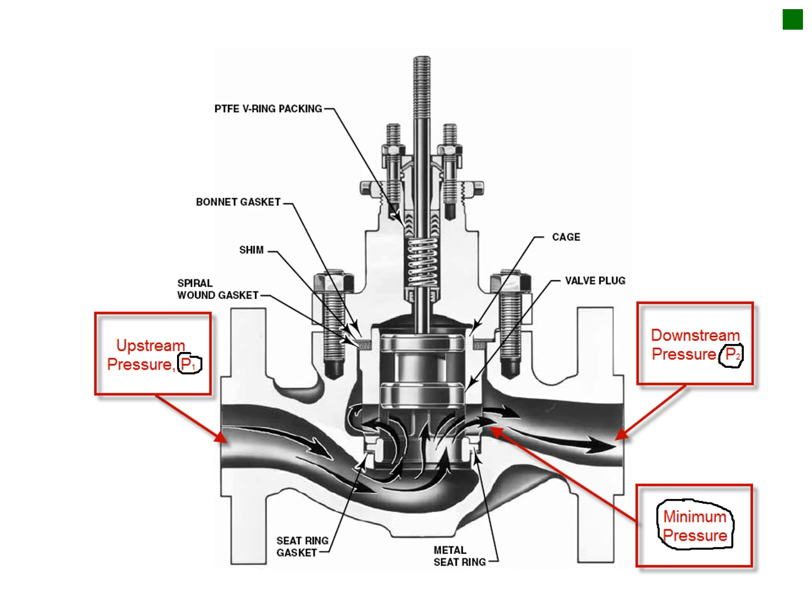Also, for flowing a gas through the control valve, the velocity at this minimum pressure may be so high that we approach the speed of sound, that is Mach 1, and that will also limit the flow rate going through the valve.